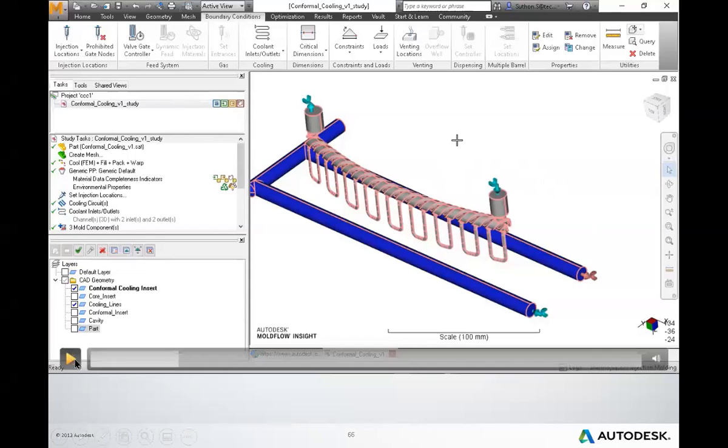After creating the inlet, okay, we can see that it is quite the same way that we have seen before. We have to set every node to have the information. So the software will indicate by the green tick mark before the icon that the process has been set already. But if one doesn't have it, such as the set injection location, we have to set this first before running the simulation. That's the key point. So if we set everything, matching everything, then we can run the simulation.